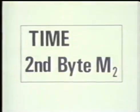The first 4 bits from ROM location 241, the middle portion of the jump address, is transmitted to the middle section of the CPU program counter. The second 4 bits from ROM location 241, the low-order portion of the jump address, is sent to the CPU where it is loaded into the program counter register.